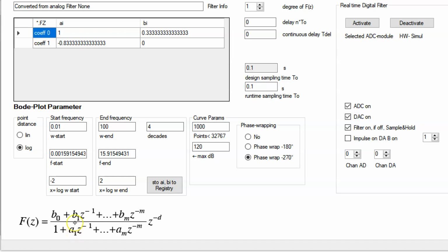That is a very simple reason. For a general digital filter it is common to use A and B. For controller transfer functions it is common to use Q and P, as I have done in our previous lecture. Note, very important, the traditional form for a digital filter with A's and B's carries here a plus sign. So a minus sign is hidden in a coefficient.